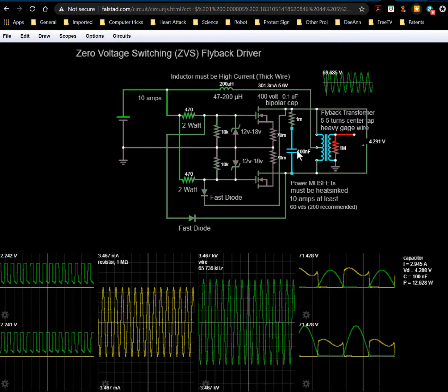Now, capacitors work in a different way. They actually store energy in an electric field instead of a magnetic field. But once you take an uncharged capacitor and put a DC battery across it, the voltage on that capacitor will start out at 0. It'll be like a short circuit. So if it weren't for the resistance you see here in series with it, it'd be infinite current. In practice, you would see a very high current trying to flow through this to charge it up in the instant you hook it up.